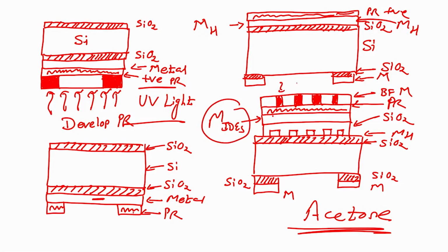After this what we will do? You will expose using UV. When you expose using UV, after that you have to unload the mask. When you unload the mask, then what you have to do? You have to dip the wafer in photoresist developer. So, when you dip the wafer in photoresist developer, what you get? You get photoresist saved in the area which were not exposed. This is photoresist which is saved in the area which was not exposed. That is, it is retaining the same pattern with the mask head.